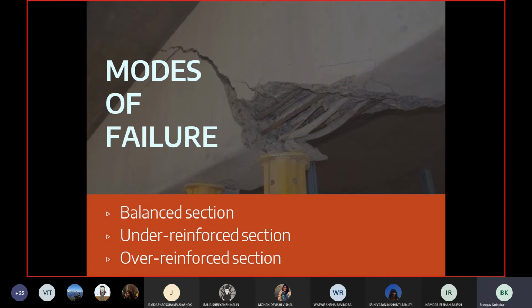So in the passive state, meaning that when the stress in the section is less than the ultimate tensile strength of concrete, it's in a passive condition wherein reinforcement is not actively participating. Only when there is cracking, concrete transfers its strain to steel by cracking.